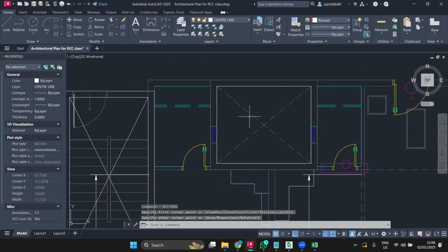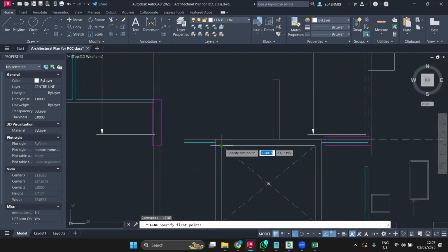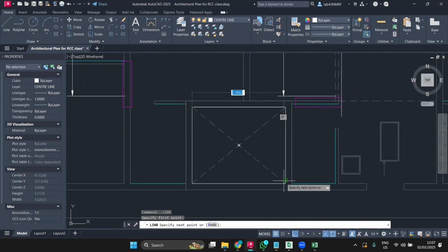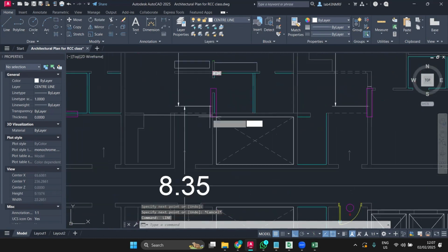The staircase will be put as an opening, right? You don't need to worry about the staircase, because we are going to draw the staircase as a slab. Remember for the waist slab, I told you? The flight is there; we are going to model it as slabs only. Don't bother about the staircase. But draw the wall line for the staircase, because the staircase and lift are RCC walls.